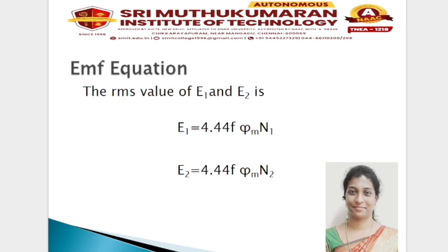Next is the EMF equation. The EMF equation explains how voltage is induced in a transformer. It shows that the induced EMF is directly proportional to the frequency, maximum flux, and the number of turns. This equation is fundamental in designing transformers for different voltage levels and frequencies.